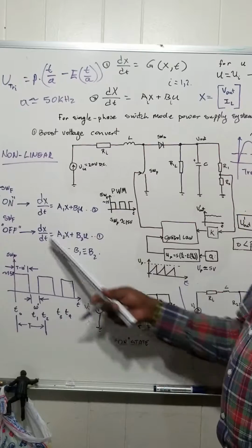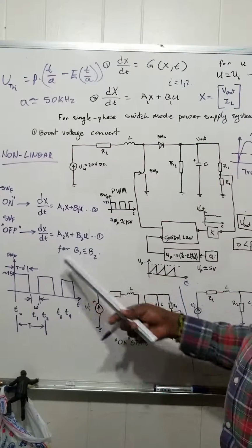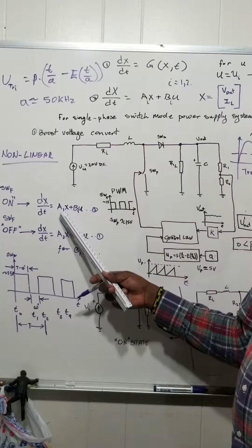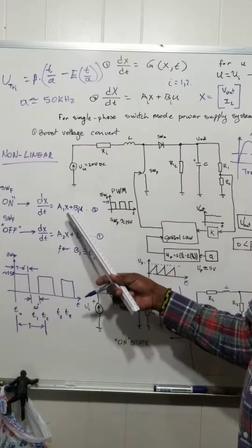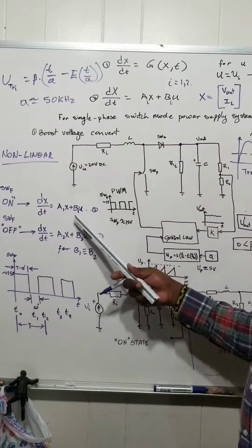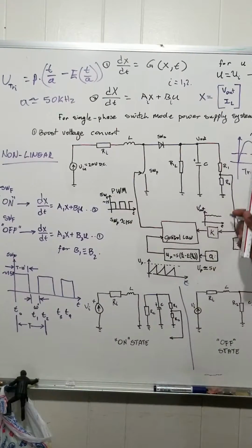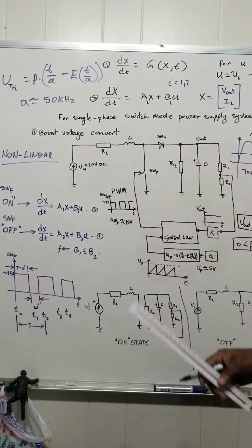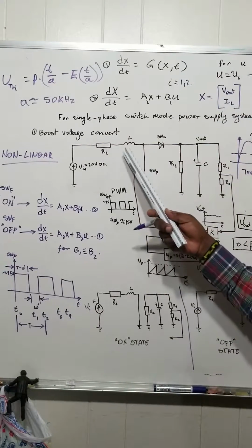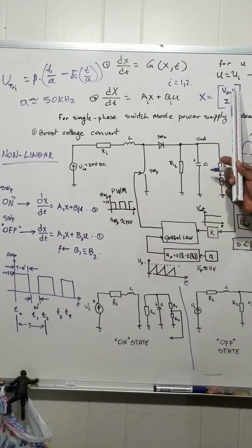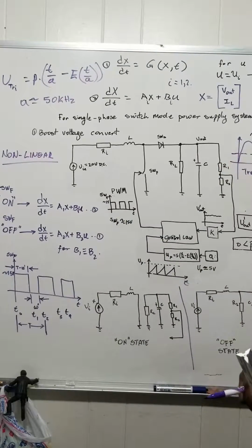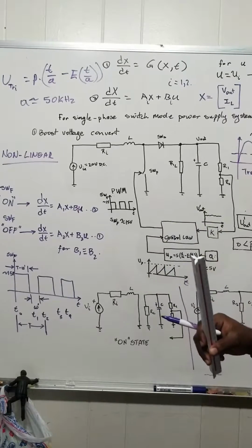But the good thing with this is that you can do certain things with this that you're not able to do with the real circuit. You can make changes within the mathematical model to the input value to see what happens to the output. And then you can compare, you can get what we call a phase diagram. What is the phase diagram? The phase diagram is comparing the inductor current and the output voltage. You get a certain shape on your graph, the characteristics, how it looks.